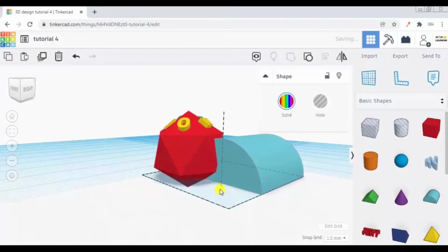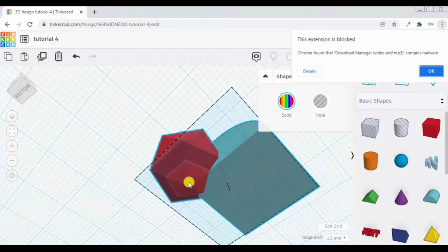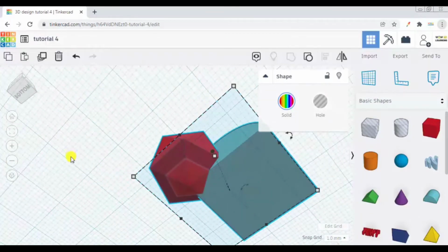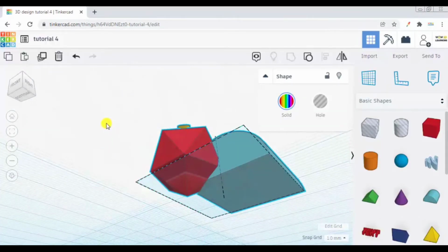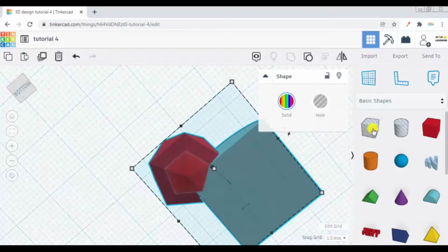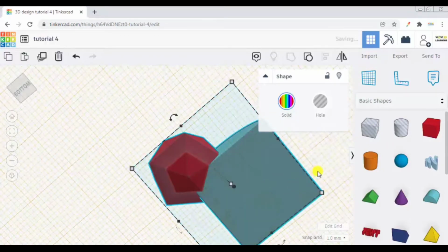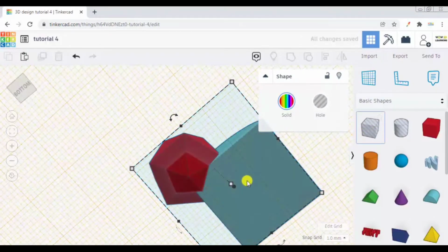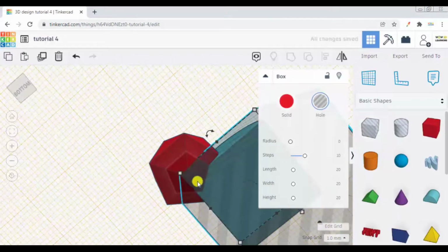Now you see, if I give the command for printing, you can see here it is piercing my print bed, but all the objects should be planar at the bottom. So for this, what we generally do is we select a hollow cube from here. I take a work plane. I put my work plane on the bottom of the roof, and here I will bring this hollow cube.